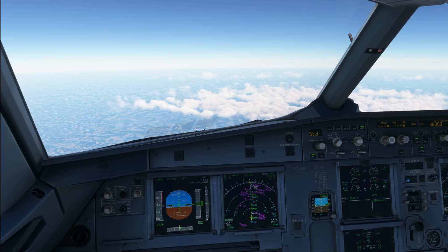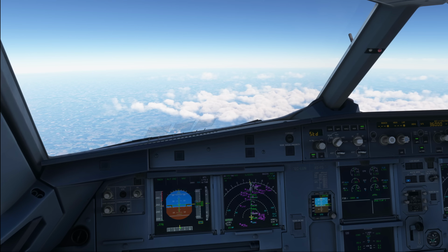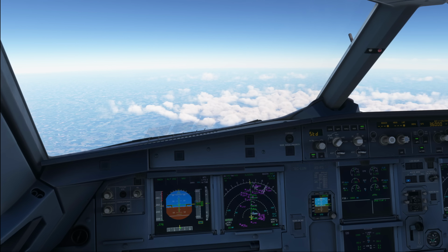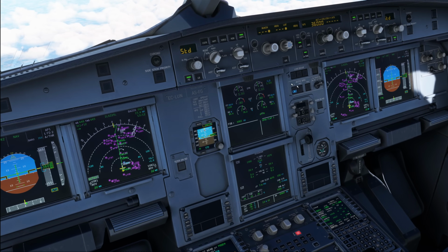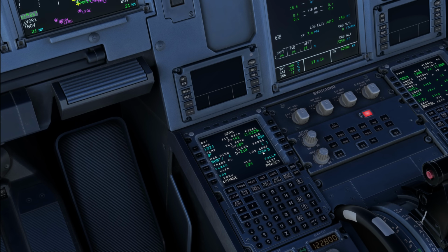The flight crew should avoid the use of auto brake medium in combination with config 3 and reverse idle. This is because this configuration highly increases brake temperature and as a result brake oxidation, which may be severe. Now, when the flight crew rides the brakes and overrides the auto brakes on landing, brake oxidation may also occur and increase cost even higher. So, recap from that for your landing planning: auto brakes low is the most optimal setting you can use, together with landing configuration 3 and idle reverse thrust when possible.